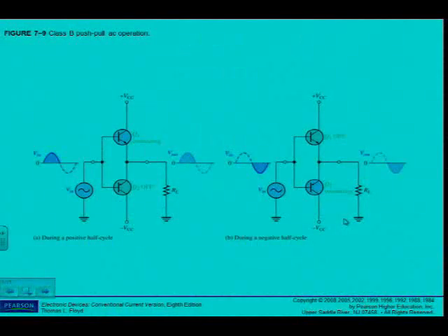There's the next one on page 331, complementary symmetry transistors. Using two emitter followers. You are familiar with the emitter follower already? Okay, so what is going to happen here? I can see here for the positive alternation of my signal, Q1, which is an NPN transistor, is going to conduct for the positive alternation.